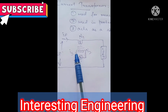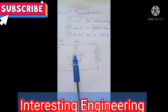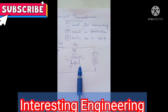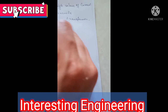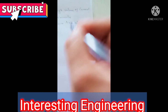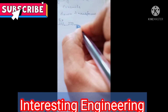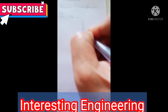In order to analyze the operation of this instrument, that is, to analyze the working of this current transformer, let me draw the equivalent circuit. In the equivalent circuit there will be a resistance, that is RP, and here we have an inductance XP. This inductance is connected with the primary.